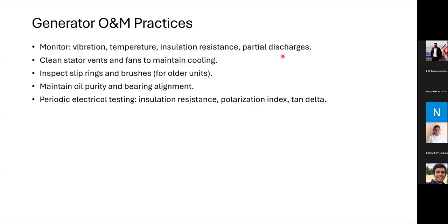And then partial discharges. These are discharges that happen into the air due to the high voltage present. In a partial discharge, there is no main arc happening. The air near the high voltage point gets ionized, and electrical discharges pass into the air, not to the other electrode. These discharges indicate that insulation failure is happening, and cause losses as well as harmonics in the stator winding output.